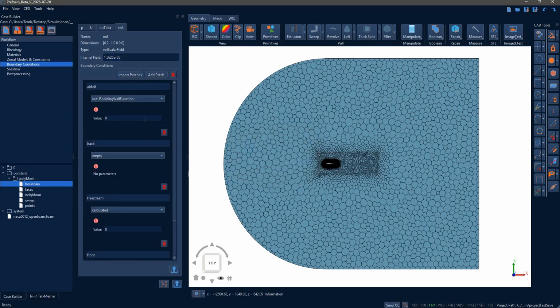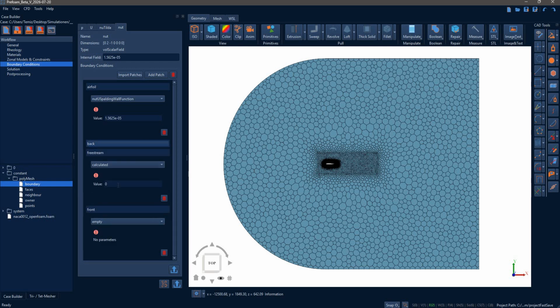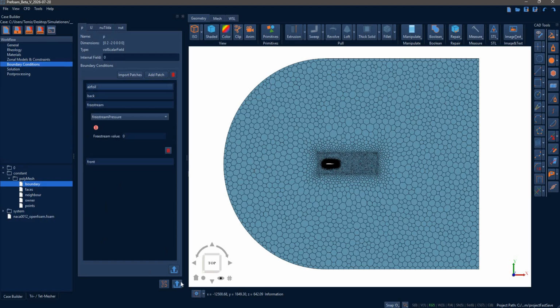Patches. So you have various options to export the files. You can export, like, let me open this, and then if you want to export the pressure only, hit this export button, and that will export only the pressure. You can also export everything from the fields. It will be these files, or you can also hit this button, and this will also export all these.